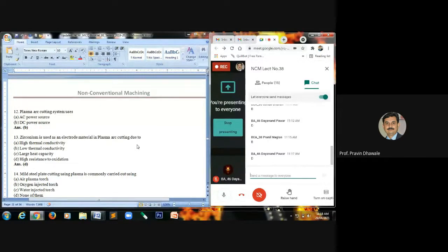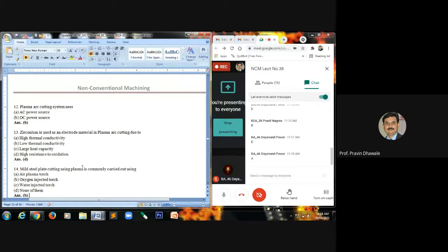Think and give the answer. That is the air plasma torch, right? Or oxygen injected, right? Mild steel plate cutting using plasma. Air plasma, oxygen injected torch, water has no relevance.